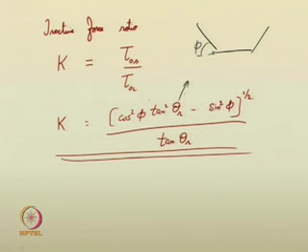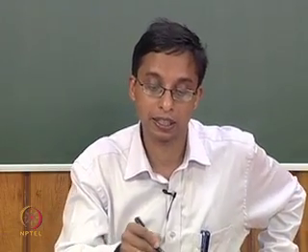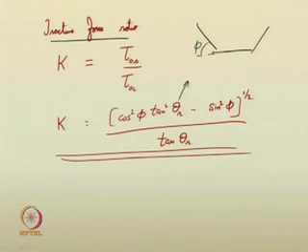The tractive force ratio does not contain any other quantities related to force, weight or friction. It is directly related to the angle of repose as well as the side slope angle. So, once you are able to identify theta r, which is well defined for any particle, and if you specify the side slope of the channel, you can easily find the tractive force ratio. Now, you can directly employ this tractive force ratio in the design of channels.